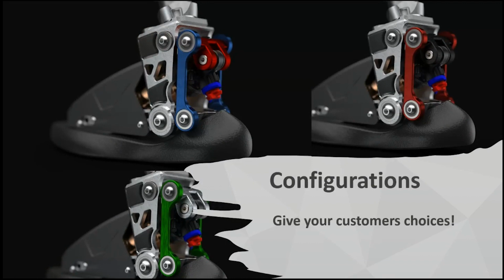I want to first talk about configurations. Now, if you're not familiar with configurations, it's basically just different versions of the same part. For example, take a pipe. You can have a bunch of sizes in the same part or project file, just as different configurations or versions.